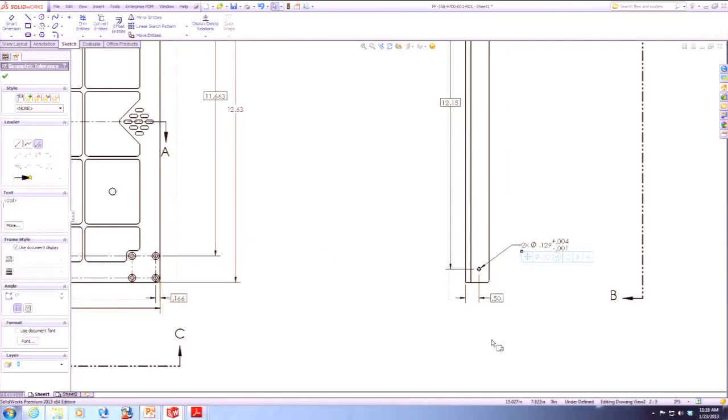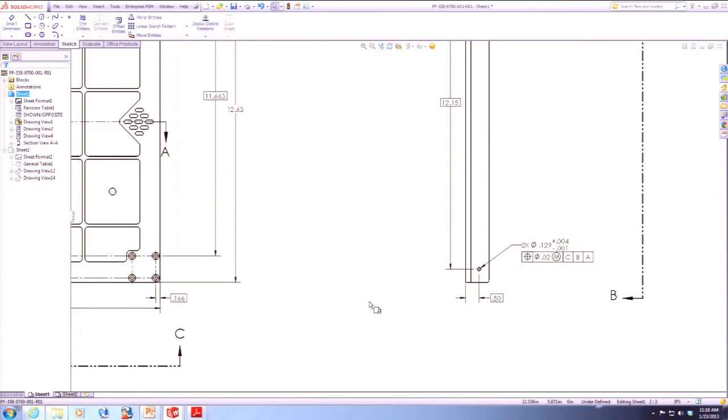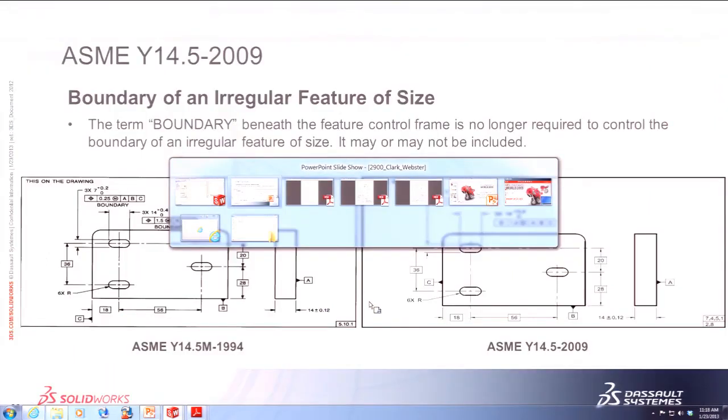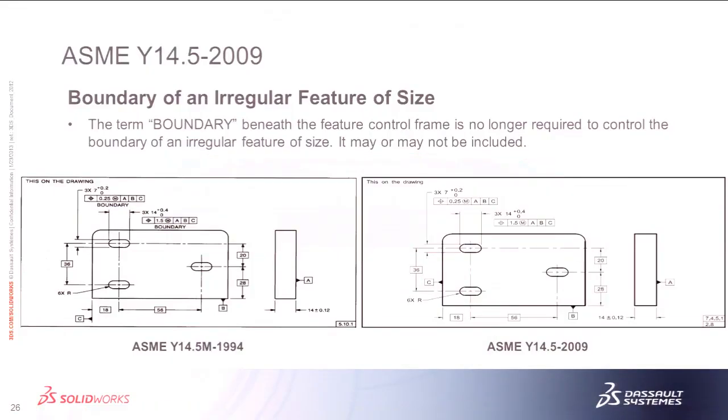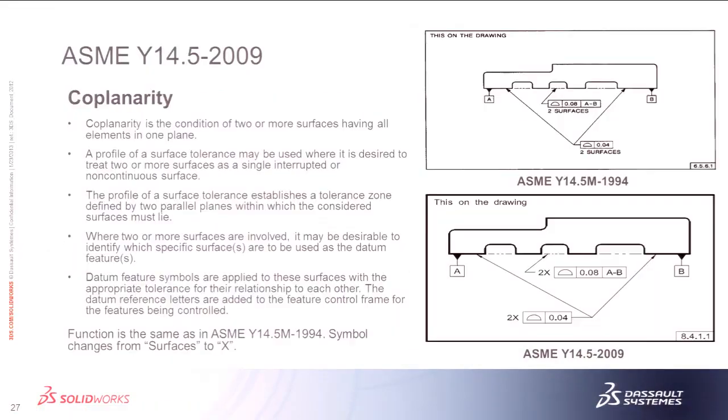And that's linked to the GD&T at that point in time, so it's not a separate note floating around in your drawing space. And I guess the reason why that's important is, you can group notes in SolidWorks, but when you actually link a GD&T symbol to a dimension, that functions as the group, so you no longer have the ability to group another note to it. So you need to actually put it in that GD&T symbol.